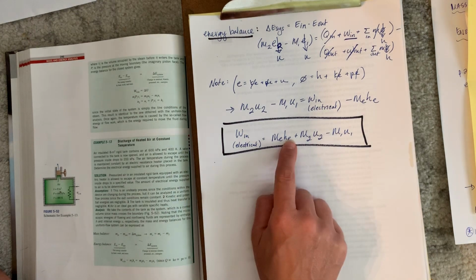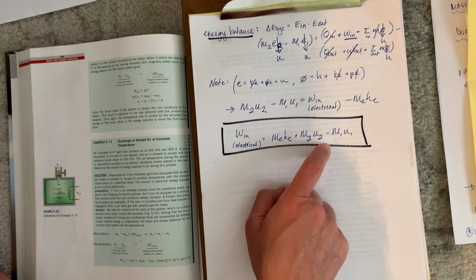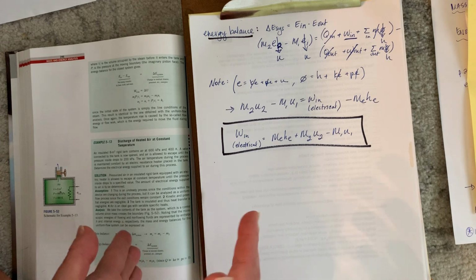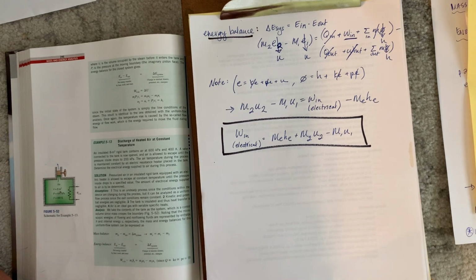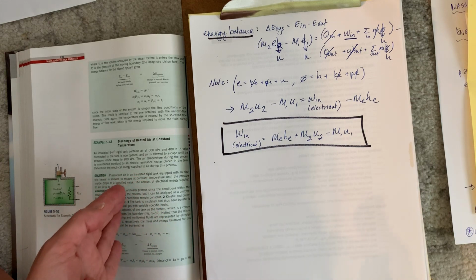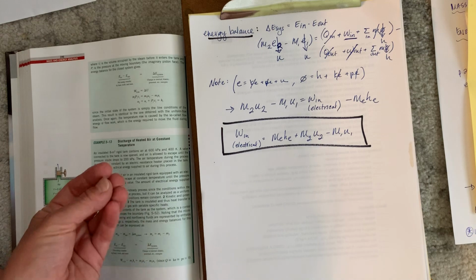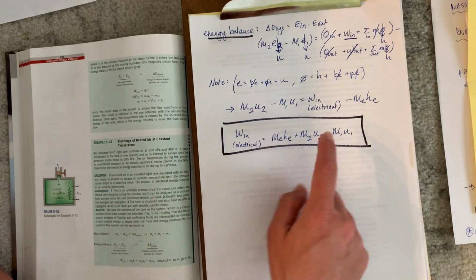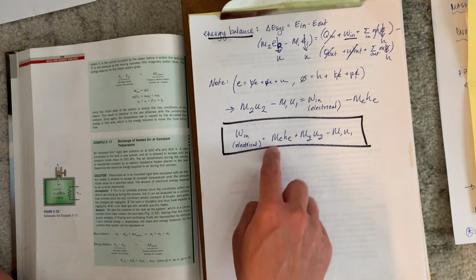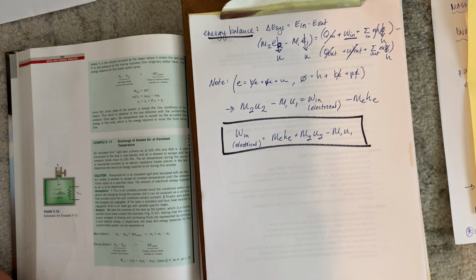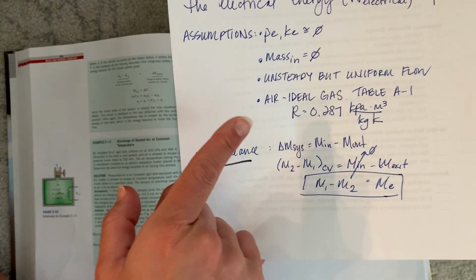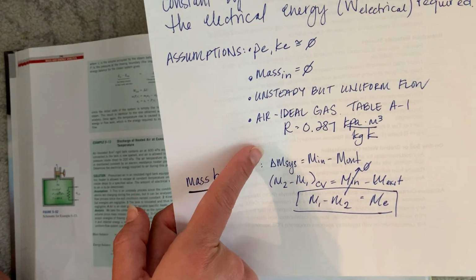Okay, so enthalpy and internal energy, you should immediately realize that this is going to require looking up in the table. We can look up with known temperature, which is not changing over time, and we also have the pressure at the starting condition and the ending condition, so it's easy to look up enthalpy and internal energy. What we need to solve for first would be mass. So how are we going to solve for mass? There are assumptions that we made right up front to make our solving for mass a bit more straightforward.